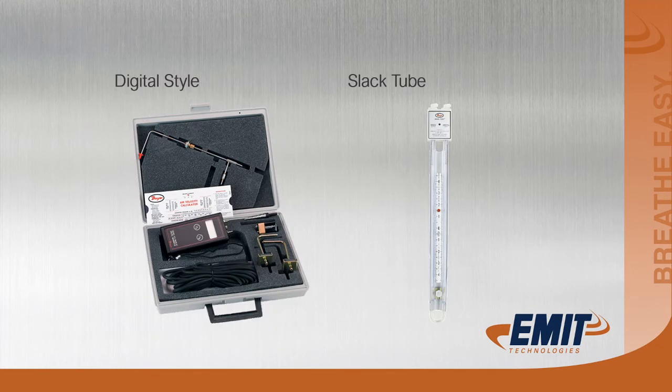Okay, and here's what they look like. Here's an electronic one on the left, and here's a slack tube, a Dwyer slack tube on the right. They both have their purpose. The great thing about the electronic is they're always readily available. They're very accurate. The one thing about them is they're slow. If you're trying to find worn regulators, that will be a problem because it'll jump around and not show it on the display. The advantage to a slack tube is you will see worn regulators or anything that's erratic, because the water in this manometer will be bouncing and telling you something's wrong, versus the electronic one, you don't always see that bounce.